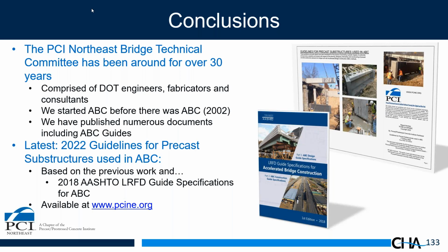The key is you want to follow the AASHTO LRFD specifications for joints, which I believe have contraction joints at 30 feet and expansion joints every 90 feet. State DOT bridge manuals sometimes have slightly different numbers, but there's no reason. We have details for both grouted joints and non-grouted joints to accommodate both contraction and expansion situations.